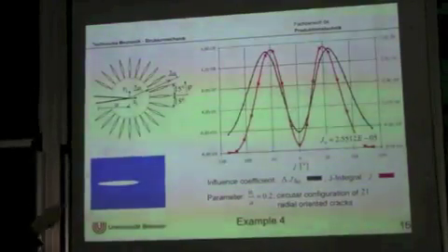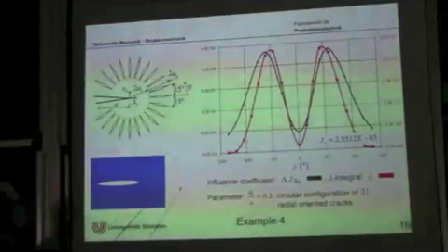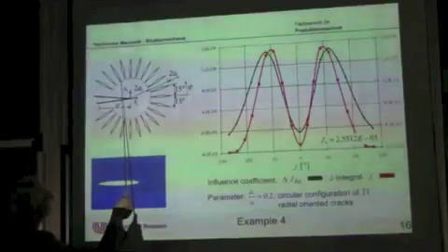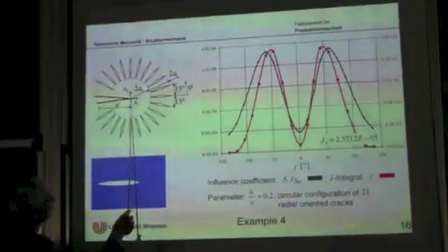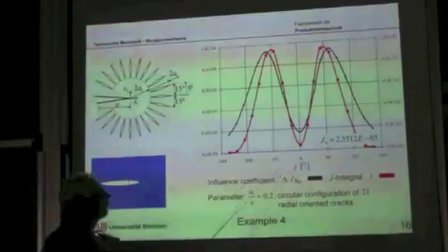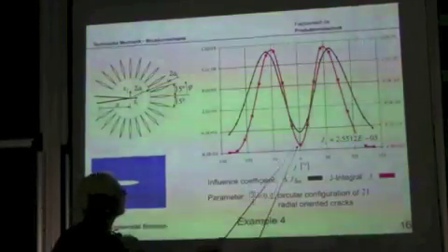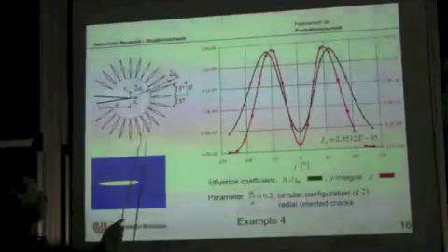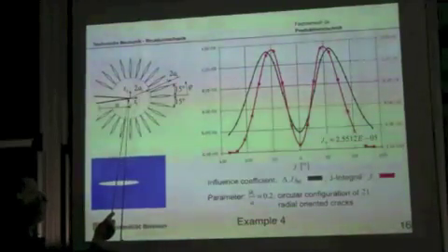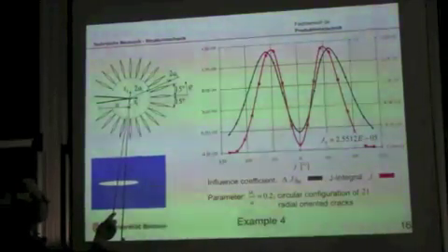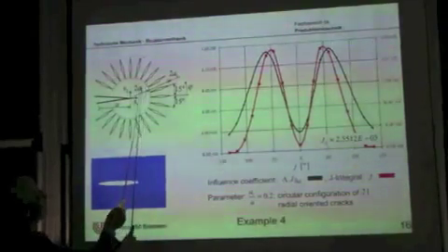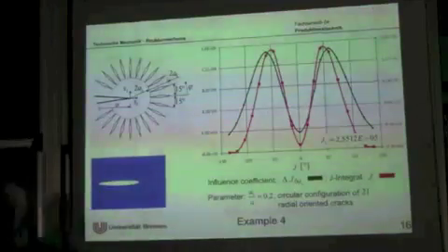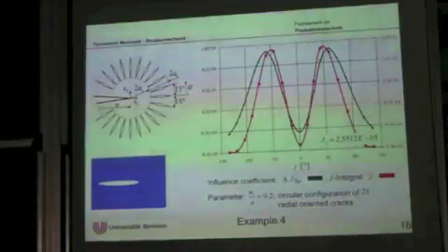And we did this also for rosette of cracks. In a similar way, there are a lot of cracks, and you see here also shielding effects. The cracks in this direction are shielding this main crack, and you find even this one, if you extend this one, it is shielded so much by the others that the J integral reduces. If you extend this crack here, you have a large effect on this configuration.